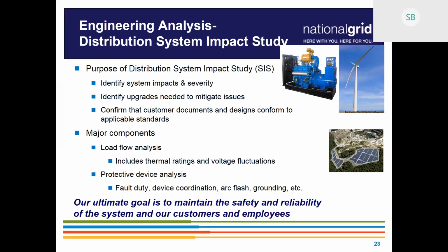Big components that we have, which I'll go into in a couple slides further down, are the load flow analysis and the protective device analysis. Those are the two main categories I would put in as far as what our analyses are. Load flow is more of a steady state analysis, looking at thermal conditions, voltage fluctuations, things like that that could be impacted by the DG. And then protective device analysis is getting into the fault current realm, short circuit, and coordination type aspects there.